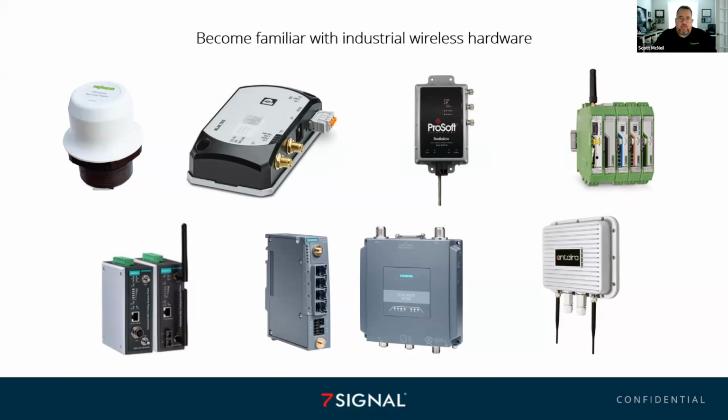But when you look at these other guys, they're completely different. Like this one, this is a little industrial radio by Phoenix Contact. It is designed to mount on a DIN rail. It is not designed to be mounted up on its own. You run your pigtails off to external antennas. And, like a lot of industrial radios, this guy is 10/100. He is not gigabit, because the throughput values that are needed in general are a lot less. You don't need gigabit throughput on your data side.